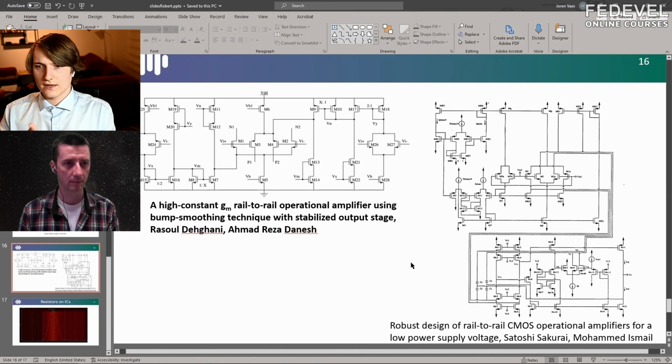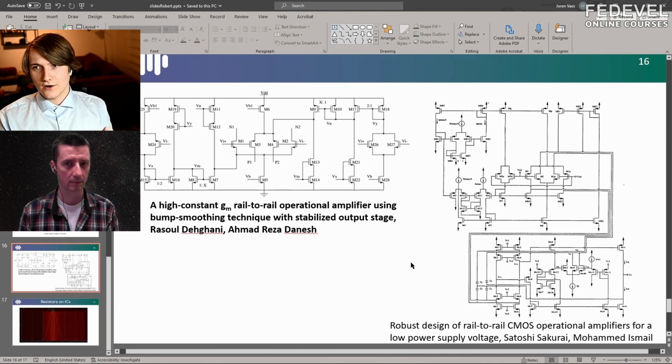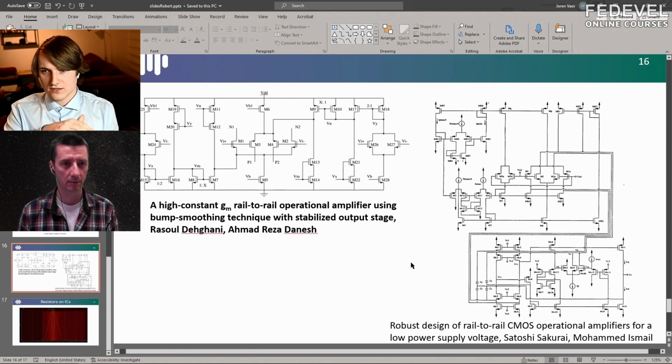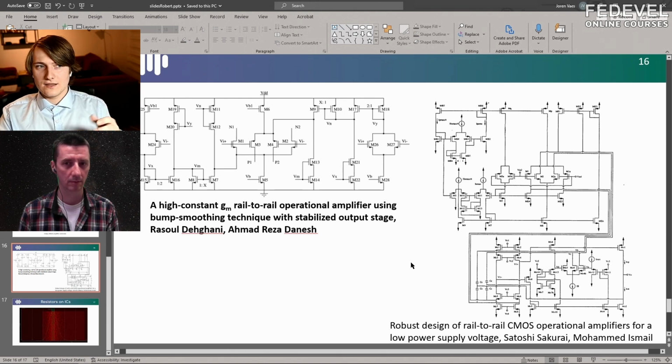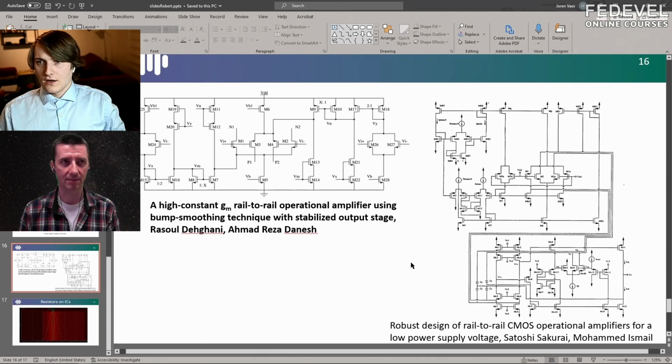Right, and this is also what, if you look at modern op-amps, Analog Devices or Texas Instruments or so on will do: instead of trying to make the perfect op-amp, they make an imperfect op-amp, but they include a digital block on the op-amp that allows them, when they package the chip, they test the chip, every chip is tested, and they can tweak it. Exactly. Sometimes they might even have a special voltage signal, so that if they turn the voltage rail on and off in the correct way, they go into a calibration mode, and then the chip knows from the measurement how imperfect it is, and it compensates for this. So it somehow uses different transistors, for example, or it changes voltages or something.